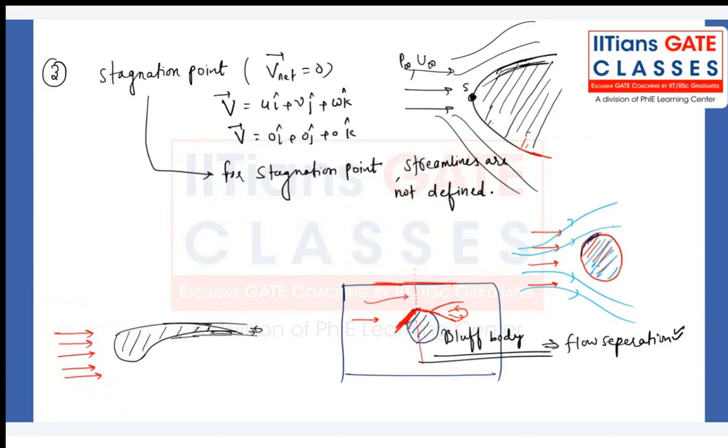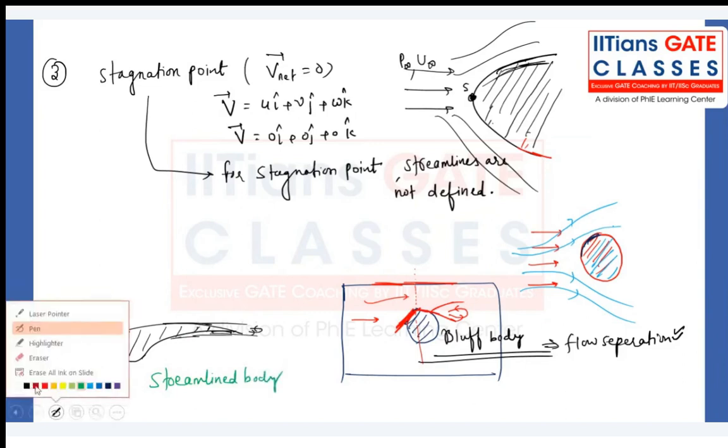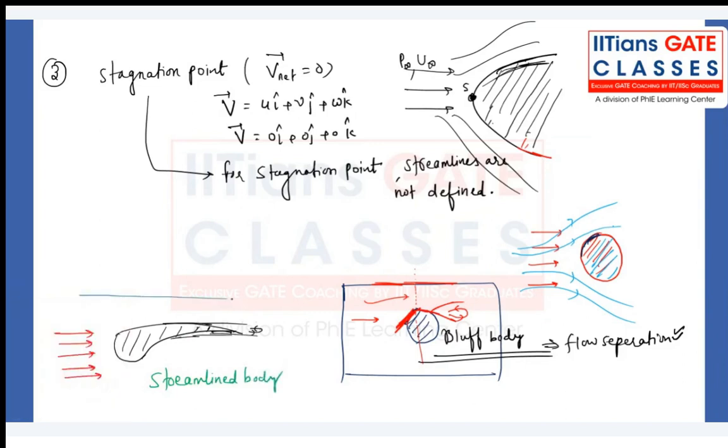Because when you draw the fluid domain and give the boundary conditions, we don't find anything suspicious. When the velocity is increasing, the areas are not suddenly changing. Just like in the ball case, suddenly the area is changing from here to something like this, working like a diverging section. But here it is happening slowly. So if it is happening slowly, flow separation will get delayed.